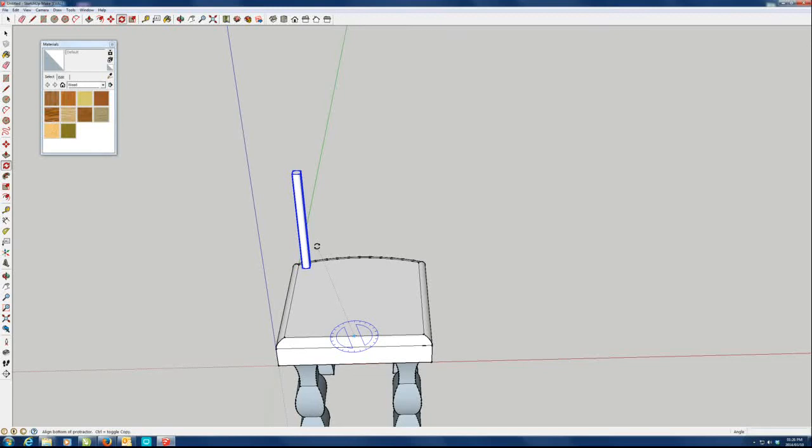Now, press and hold the control key, click on the pole, keep holding the control in, move the pole to its final position over there. Now, without clicking anything else, we're going to use the array function to insert poles between there. You press 4 and divide. You'll see it over there in the corner, and press enter. Alright, I took too long, so let me copy this again.